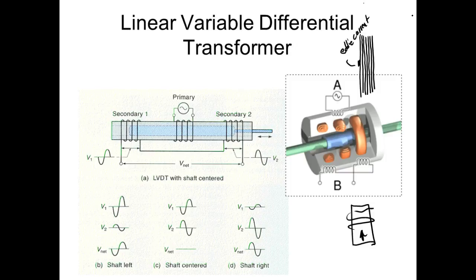It's a good insulator, but the problem is that it can burn off really easily. A lot of times in transformers, they get way too hot and it burns a little spot and burns two windings together. Now you've shorted stuff out, and as soon as you short out one of your windings, the transformer doesn't give you what it's supposed to give. Every winding you short acts like one winding, and you lose one of your windings in your ratio, right? And usually it just cascades after that. Now the transformer pulls more current, which means it gets hotter, which burns off more lamination. That's usually what happens, even in motors.